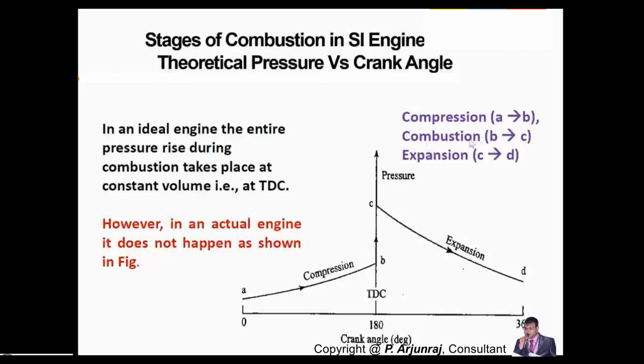And strictly speaking, with respect to the valve timing diagram, we have seen 15 degrees before top dead center, or 20 degrees. Again, the limit is there, so I'm assuming 15 degrees. Before top dead center, before the compression stage, you are going to ignite a fuel or inject a fuel according to the engine type. The pressure shoots up, right? The pressure shoots up.